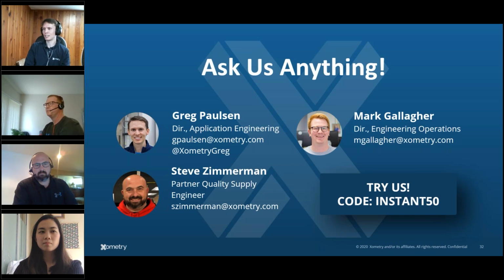I think it's a very good one. So you could have this and put something like "dimensions for reference only." This is more common in stuff like additive manufacturing, really, but turning everything into a reference dimension, so those dimensions with parentheses around them, helps us for spot checking, but it's not necessarily rejection criteria against those parts. If I did not answer that question well, shoot me an email and I'll make sure to answer that.